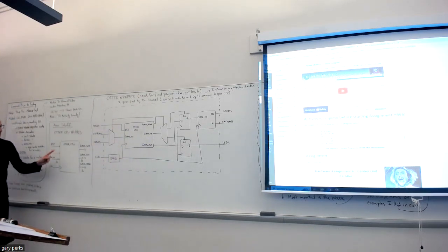And you can see that the Otter CPU just has a few inputs and 3 outputs. Over here on the input side, we have our reset input, our IO bus in, and our clock. Now, the interrupt input is in red because we're not covering interrupts. We're not dealing with interrupts.